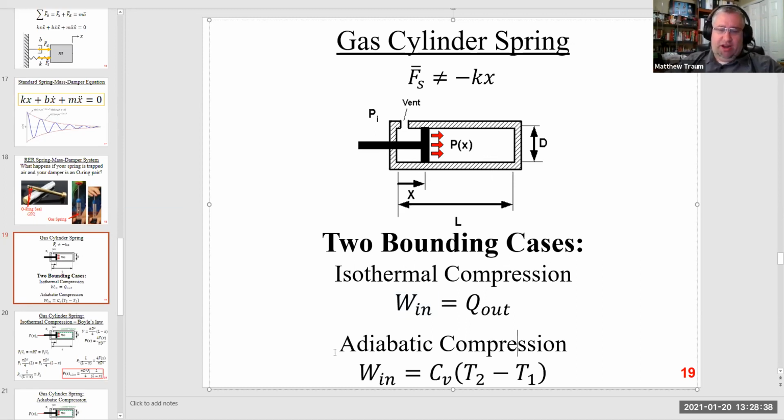The other extreme is an adiabatic compression. This is the one that you actually do if you're compressing to try to get the fire tube to produce an ember. There are two ways to do this. Either you could just do it really fast, so you're compressing the gas so fast that it heats up and doesn't have time to transfer heat to the walls of the chamber or to the ambient environment before it hits the auto ignition temperature and causes the char cloth to spark. Or you could make the cylinder out of something that's insulative, because that's what adiabatic means. Adiabatic means no heat transfer.